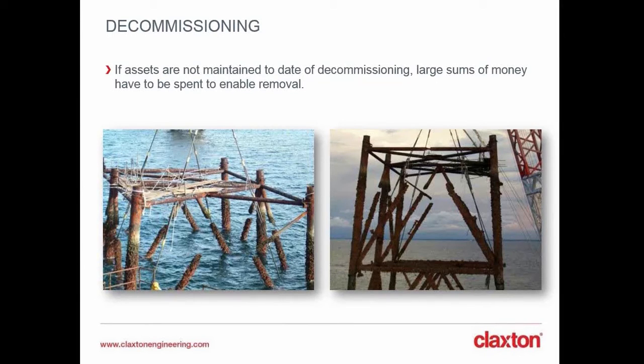If you see the pictures there on your slide, there are a couple of examples where the decommissioning phase was quite a complicated one, and that, as you can see, was because of the condition of the platform. The number of cuts and lifts greatly increases when there's uncertainty about the condition of the different structural elements. And as you can imagine, in a case like the one shown in the picture, something that could perhaps have been done a lot easier and safer basically required an incredible amount of work and planning.